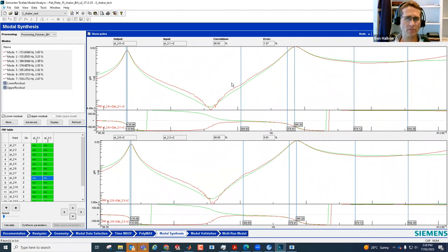Right? When we did quadrature peak picking, just using FRFs and looking at the imaginary part, extracting the value of the imaginary part at the peak, and using that to plot for each of the frequencies the levels of vibration of the points on the structure. This is exactly the same process essentially that we're going through here with modal analysis in a commercially available system. You can think of it in the same way.